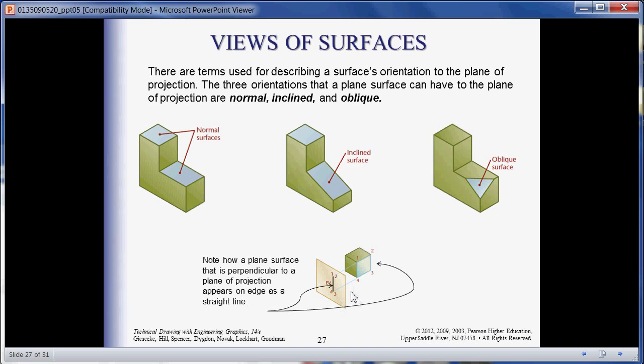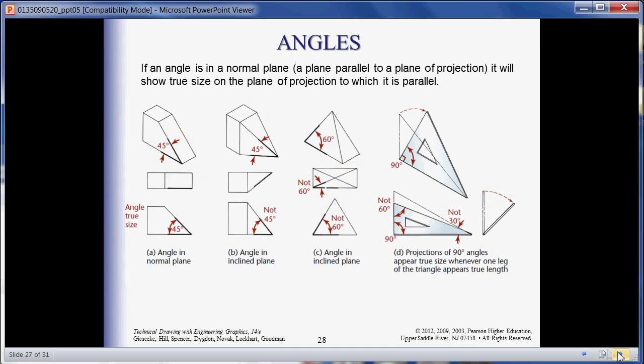Okay. But let's take a look here. On the side view, and it makes sense, and we know this intuitively, this face here eventually becomes this line if it's turned on its side. Now this line turns into a point if I'm looking down at that face. So if I'm looking down on the top view, this line becomes a point right there, point 1.